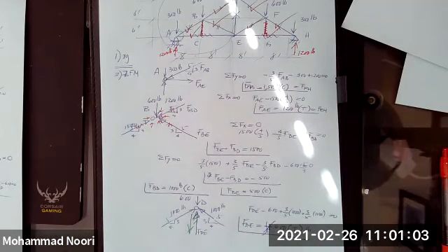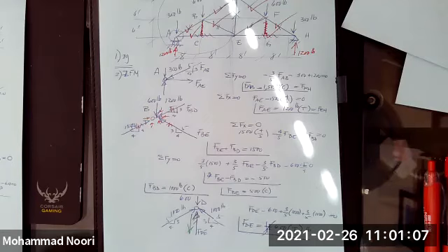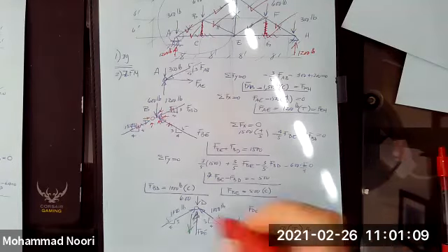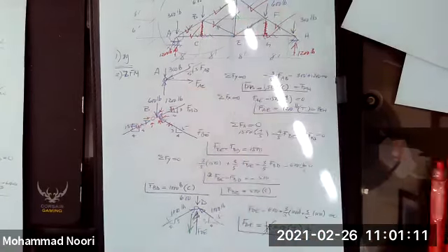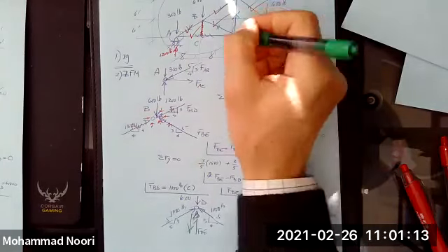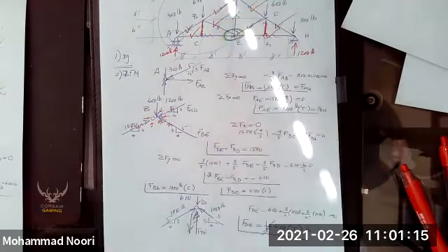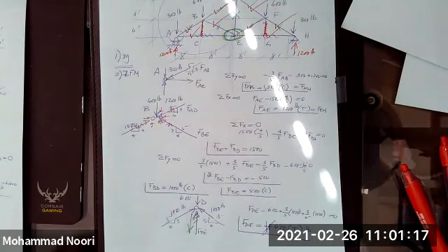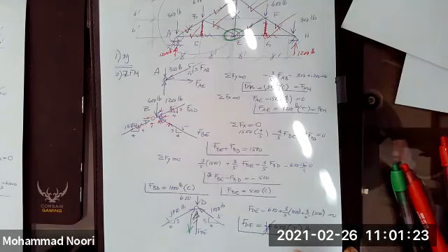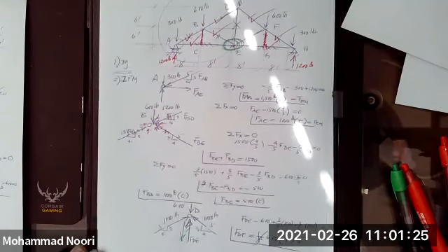And you solve for all these forces. If you want, you can use one joint that you have not used, and that is this joint, to verify your answers. And I bet you if you do that, you see that the answers are going to be confirmed. Any questions?